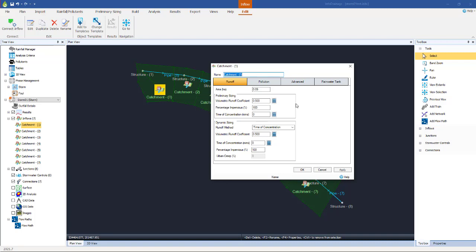And remember that we only get a rainfall contribution from developed catchments, so the roads, the roofs, the hard standing areas. So a typical suburban environment is going to be perhaps 60 or 70% impervious. It's not going to be 100. If you were designing a manhole sitting in the middle of a big runway, or you were doing a huge storage warehouse perhaps, then possibly you get up to 100% imperviousness, but in a typical urban environment it's going to be a lot lower than that.